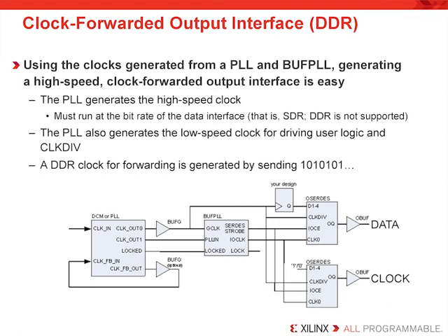For higher serialization rates, up to 8, each output SerDes can be cascaded with an associated slave output SerDes. The outputs can be implemented using any I/O standard, but for higher data rates, it is common to use the differential I/O standards such as LVDS.